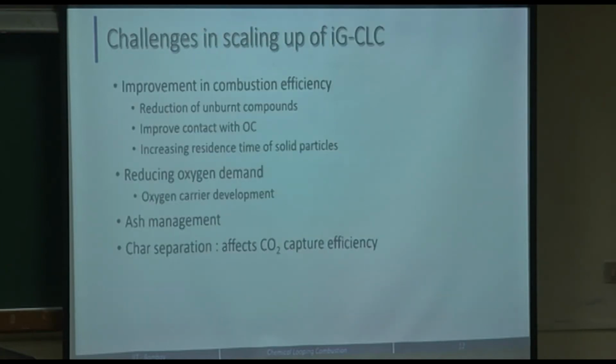So the challenges would be to improve the combustion efficiency, and the oxygen carrier development is again a huge research area. There are lots of materials published for different kinds of oxygen carriers for different temperatures and different strengths, and again ash management is an issue. And as I discussed, I find char separation a challenging thing, because it directly affects the carbon capture efficiency, and if it affects this, then there is no point of CLC, because CLC has the major advantage of getting a pure CO2 stream. So I think that's it.